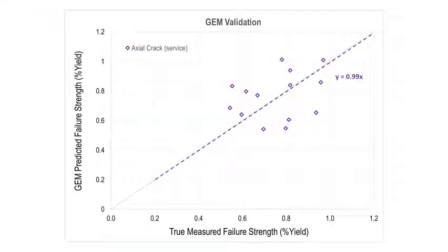So first of all, we'll look at the fatigue cracks. You'll find that the overall accuracy is pretty much right on the money, maybe a tiny bit overly conservative. What you notice here is that there's a lot more spread in the data, and that's really just the nature of the beast when you're dealing with natural flaws that have funky shapes, or you may have a little bit of residual stress acting near the weld. There might be some peaking or weld mismatch that makes your numbers go off a little bit.